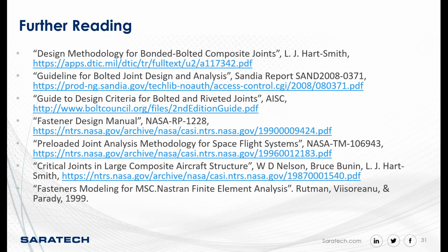How do you recommend modeling a 3-flange assembly with threads in flange 3, a washer on the outside of flange 1, and only a through hole in flange 2? I hope I said those right. A single shear is relatively straightforward when you have just 2 members, but as soon as you start getting to 3 members, and especially have different thicknesses and different moduli, then what stiffnesses do you use? You may actually end up with different stiffnesses because you'll have multiple elements representing a fastener.